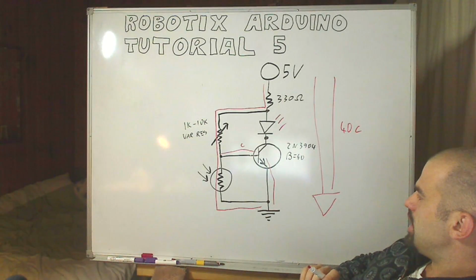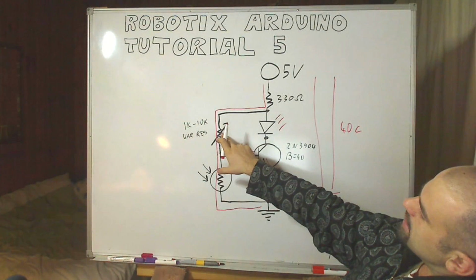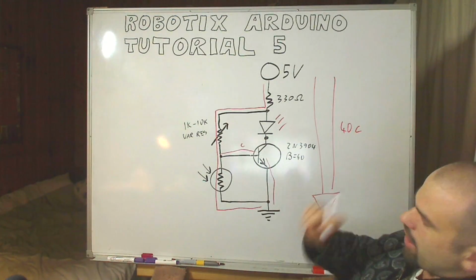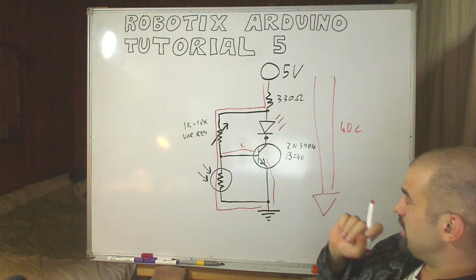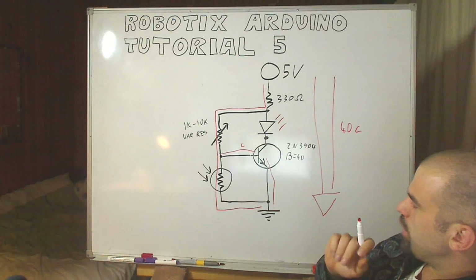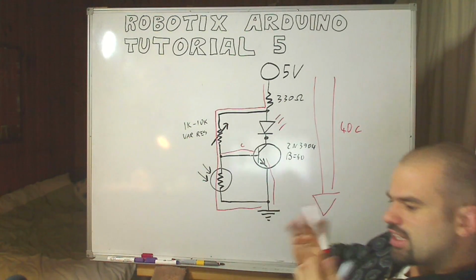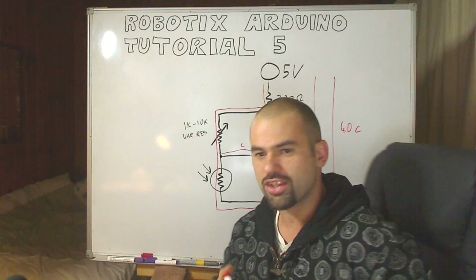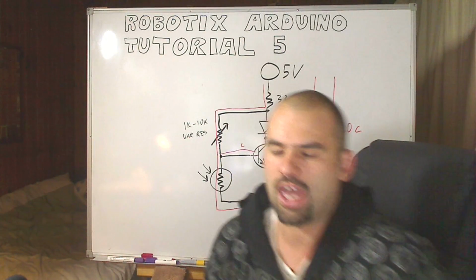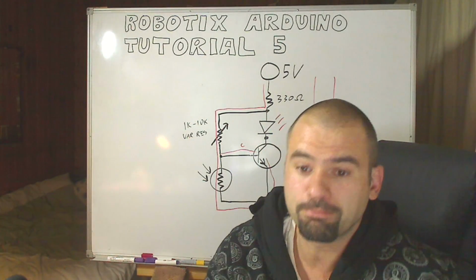So in other words, when we make the circuit, we will turn this variable resistor to the point where the light just goes off, so that every time a shadow passes by, the light should be able to come on. So it's just like the previous circuit, but it's rather sensitive to light and should be much more fun to play with. Let's get to building it.